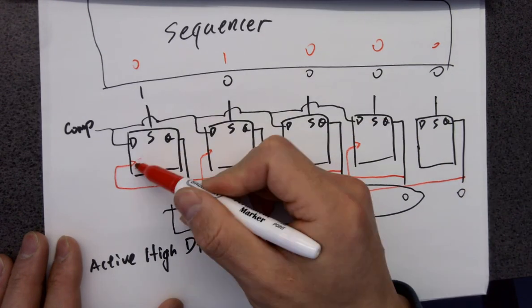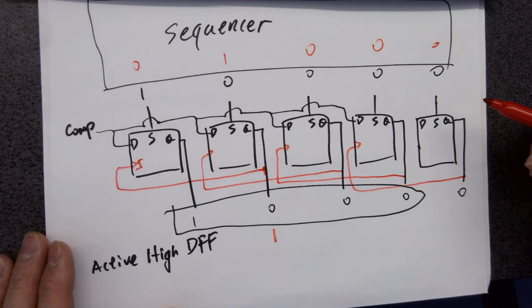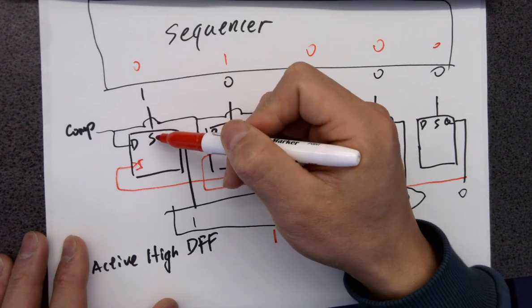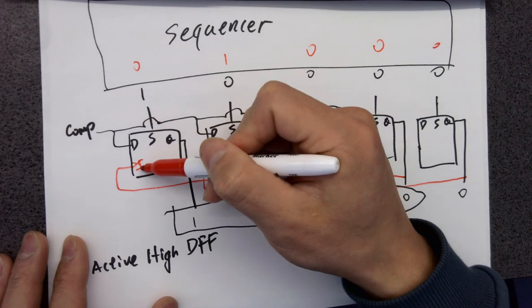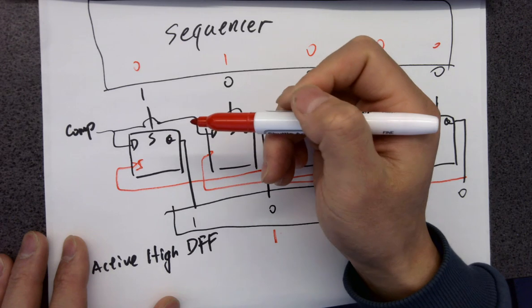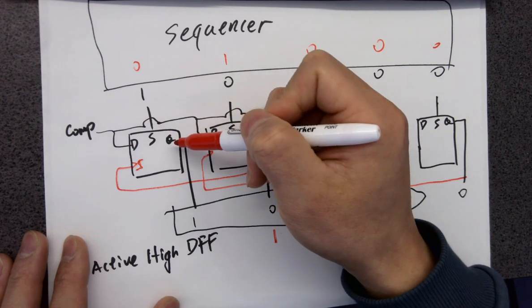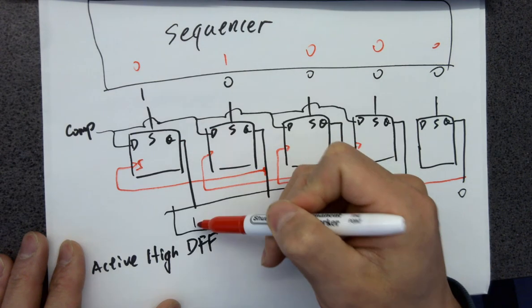And that rising edge is going to do what? It's rising edge triggered. And now it's 0 at the set pin. So the D flip-flop is not being set. So it's operating as a D flip-flop. So the rising edge is going to do what? It's going to take D to Q. It's a data flip-flop. It's going to pass D to Q.